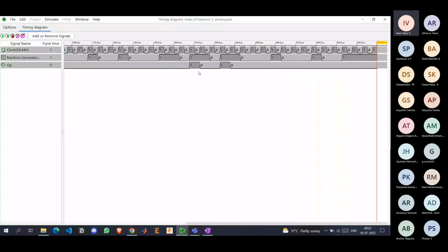See, it again detects the sequence. Whenever we have a dip like this, from 1 it goes to 0 and again goes to 1, our sequence detector will detect it. Again, the next time, it goes from 1 to 0 and again to 1. Not having two zeros, only one 0. This line represents 1 0, but these two lines represent 1 1 0 1 1. But we have 1 0 1, right? If we check the last three inputs, it will be 1 0 1. So it detects.